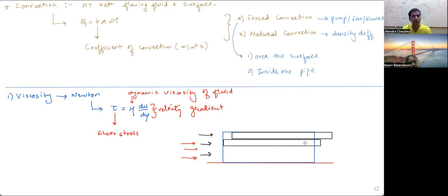These are exaggerated forms of the layers. They are really thin. But if you understand that whenever there is water or some viscous fluid on this plate or surface, and you tilt the surface, you can still see that some part of the fluid is stuck to the material. That is the lowermost layer. So this is how we can represent that the upper layer proceeds, whereas the lower layer tries to remain at its position, and that's how adjacent layers get sheared from each other.